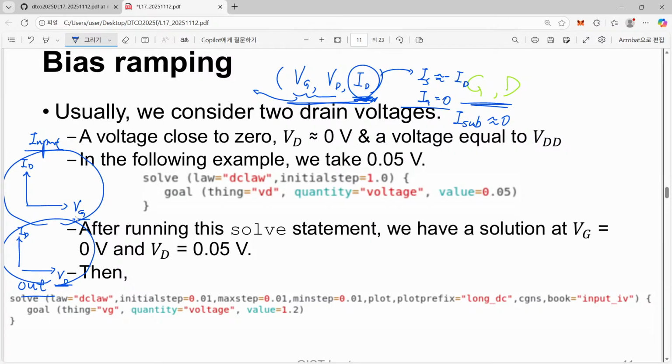For that purpose, when we change our gate voltage, we must have a fixed value for drain voltage. So before starting increasing or changing gate voltage, first of all, we have to arrive at that target value of drain voltage. So before starting changing gate voltage, first increase drain voltage. Up to what?